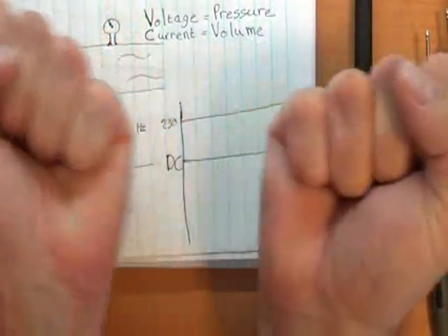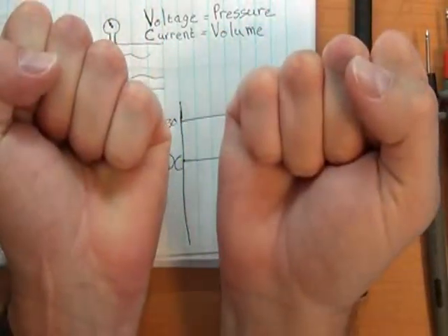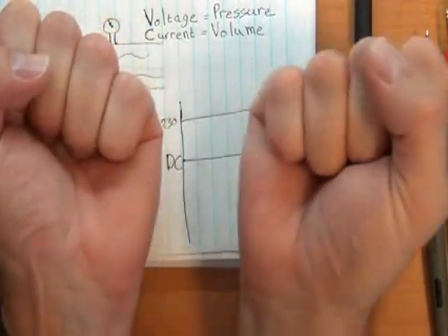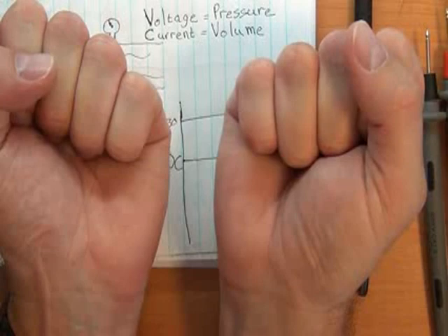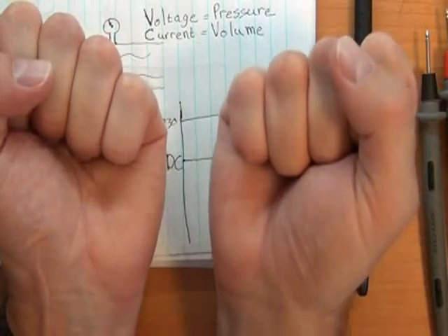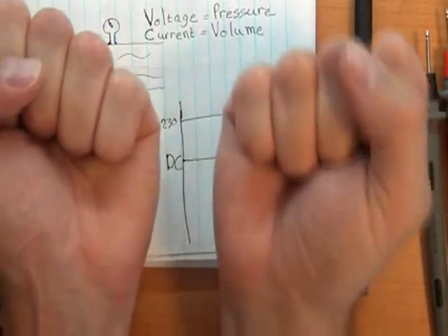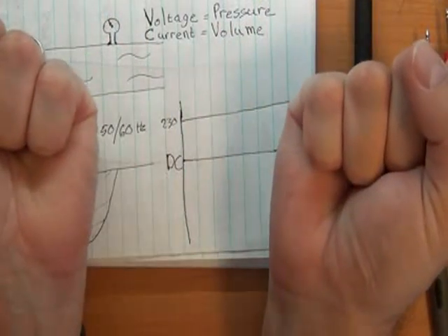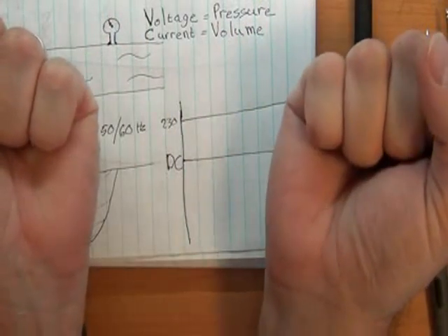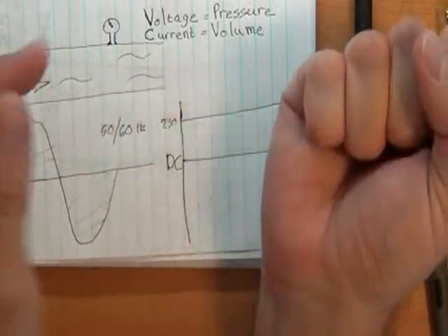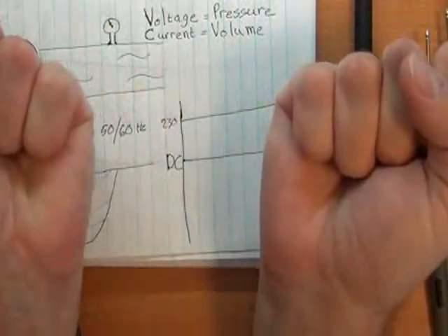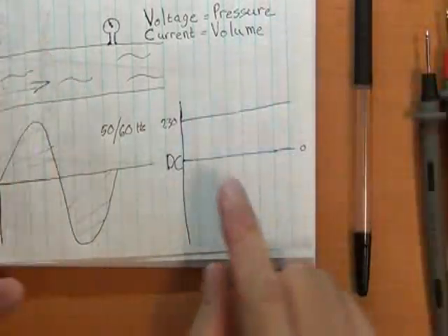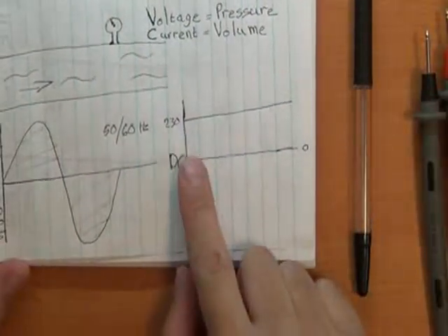If you had the wires between two solar panels linked in series with that high DC voltage, and you had a continuous circuit, i.e. you didn't break it somewhere, and you had current running, and you pulled that apart at 600 volts, you would potentially be in for a lot of trouble, because it would arc. It's like lightning. It would arc between those two contacts. So that's where you have to be very careful with high voltage DC.